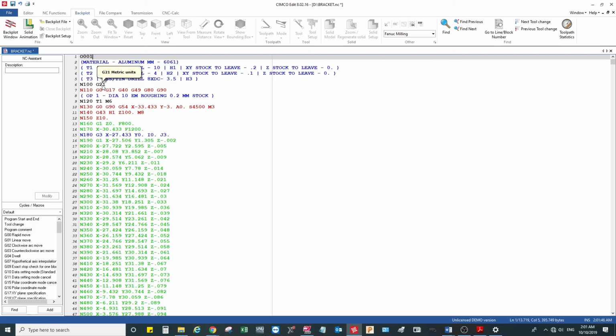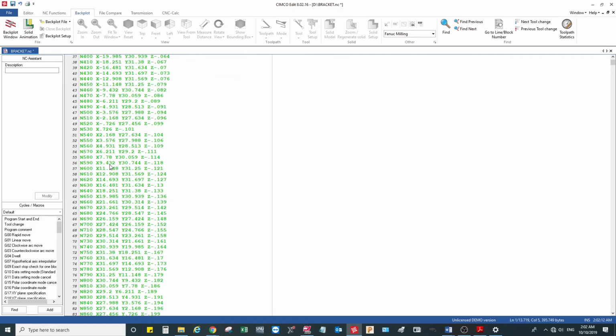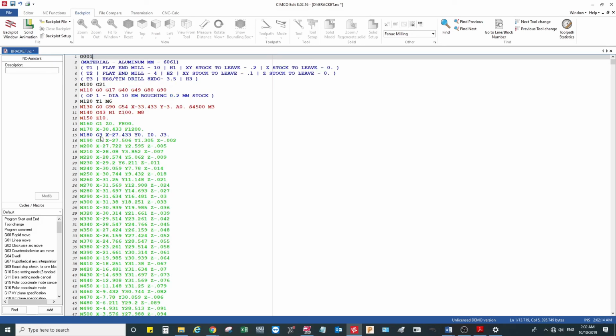All right. So I still have about 0.1 stock in here, which I can machine using a different toolpath. I will just go with the contour toolpath and get that 0.1 stock removed as a finishing pass for this particular operation.